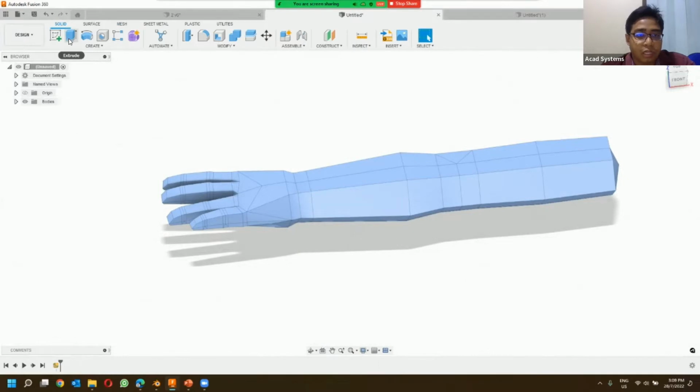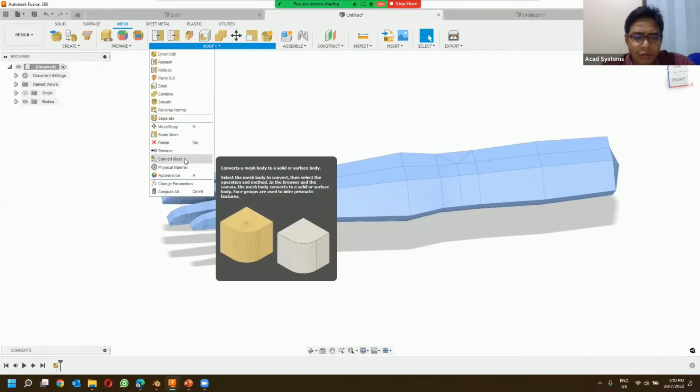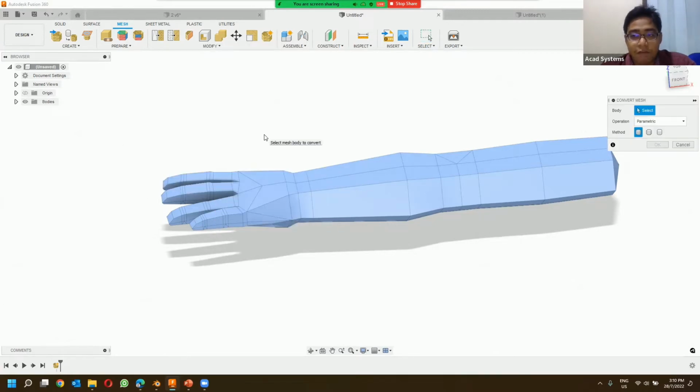You cannot use extrude, you cannot use press pull, some of those things, so you can only work with the mesh. So from the mesh, I want to convert it into a solid. For that, you can go to the modify drop down, and then you can convert this mesh into a solid.